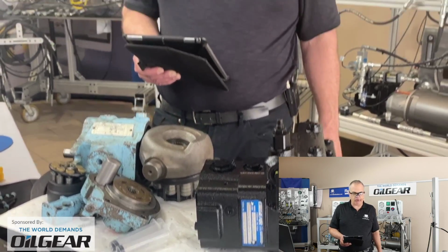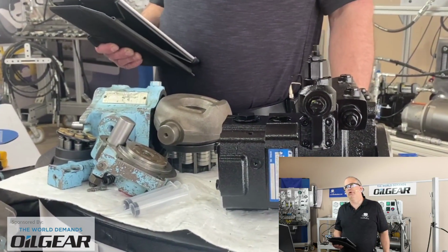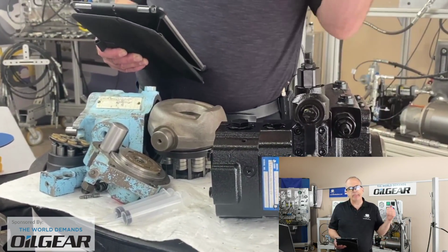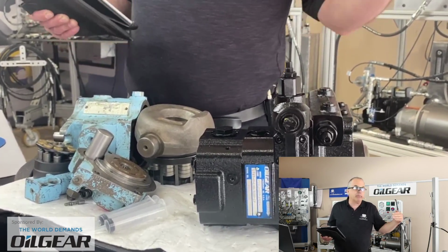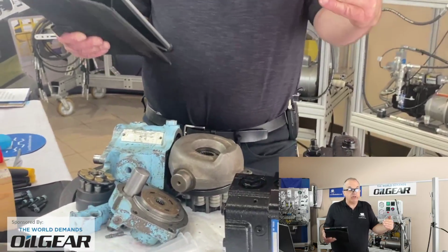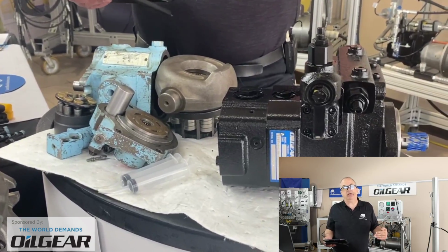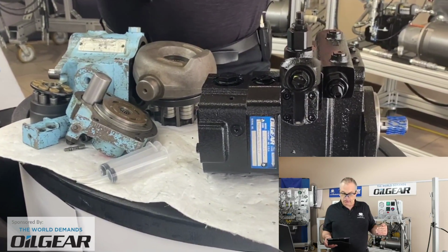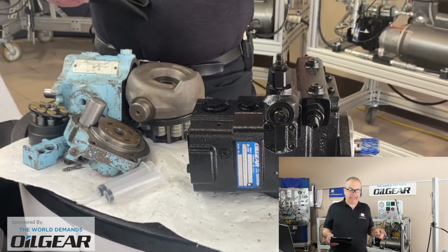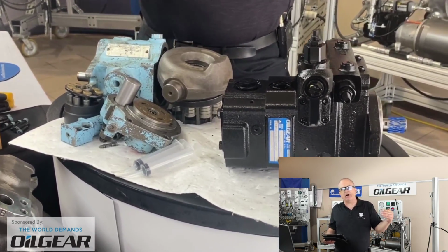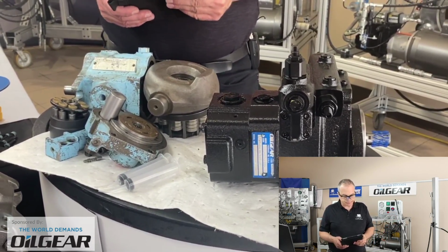There are machines out there where that Q minimum is moved away from the 0-degree angle to produce a certain servo or control pressure throughout a hydraulic system, where a number of other control valves will need to react when the system is kind of in a low, almost a neutral state. And so yeah, sometimes that Q minimum that you asked about is moved off of 0 just a little bit to make it easy to produce a higher piloting or standby pressure. Yeah, good one.